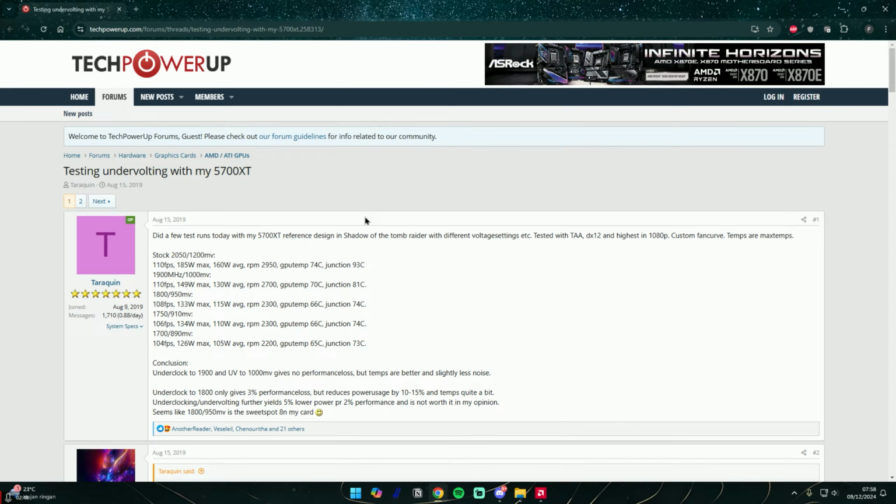And the best undervolt setting that I prefer, that balances out between the temperature and the performance, is this one right here. Although this is a bit lower clock setting, it does give a very good temperature on my card, which I'm not worrying about. It loses about 2 FPS compared to stock settings, but of course, this will vary between different games.